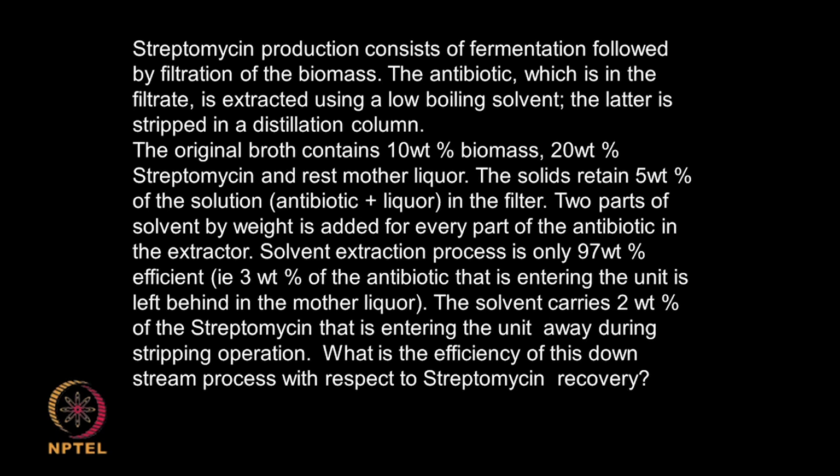So, that 5% of solution will also contain some amount of antibiotic and some amount of the liquid, in the same 20:70 ratio, because in the original broth you have 20 streptomycin and 70 mother liquor. So, you are going to lose some amount of streptomycin in the liquid which is retained by the biomass.